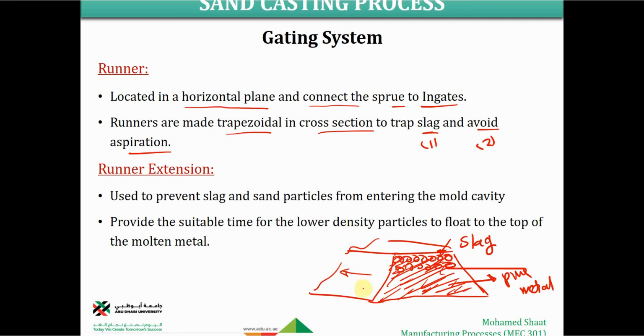Then what we do, because there should be a runner, and over the runner we open a small opening here. This opening should be the in gate, or the gate. So what happened here? Basically, we open a small opening over the runner through the sand, where the molten metal should be very close to the base. Why the base? Because the molten metal is already located down. So the metal is going to go through the in gate, and the in gate is the gate to the mold cavity. This is the opening directly to the mold cavity.